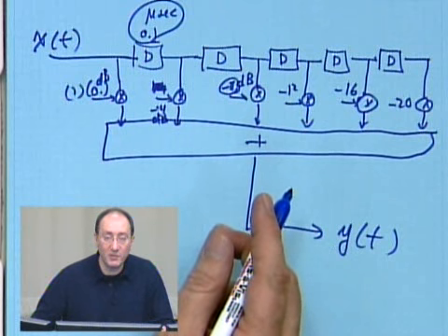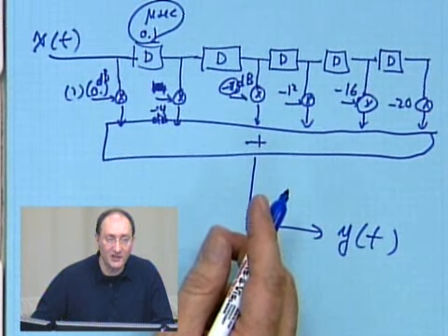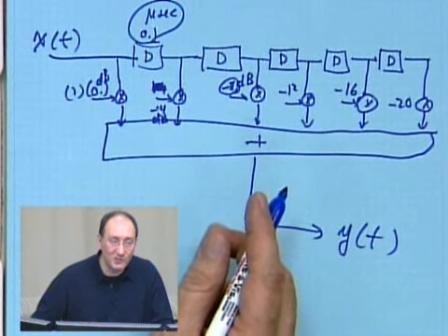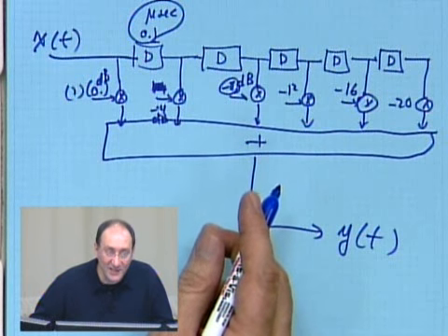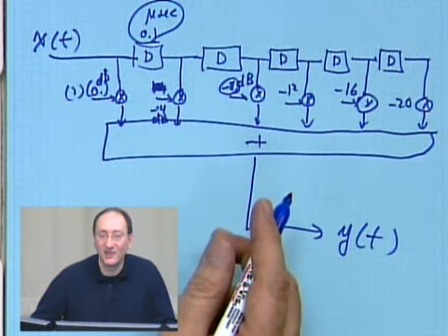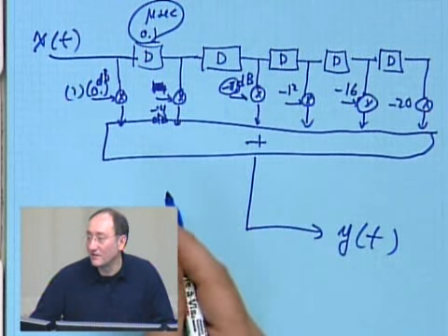Now you can see why people give you 2 options. You have the 6 tap option and the 4 tap option. The 4 tap option is simpler to implement, but you try to keep the RMS delay spread the same. So you have 2 options to implement it.